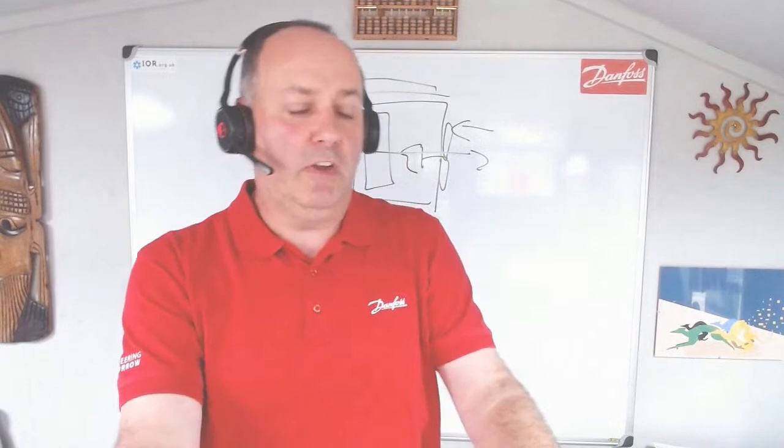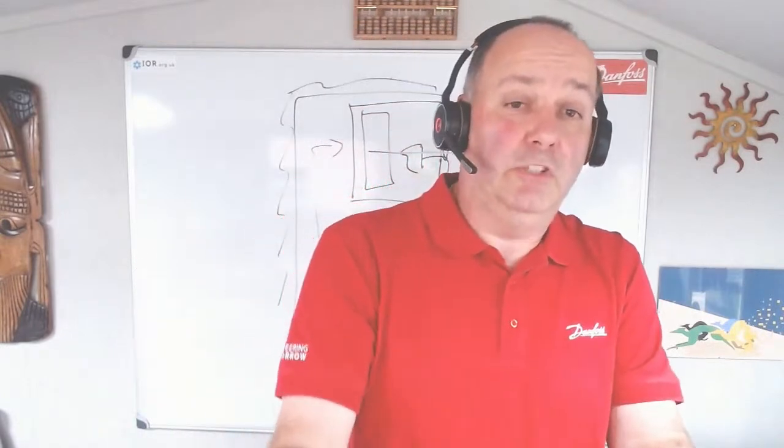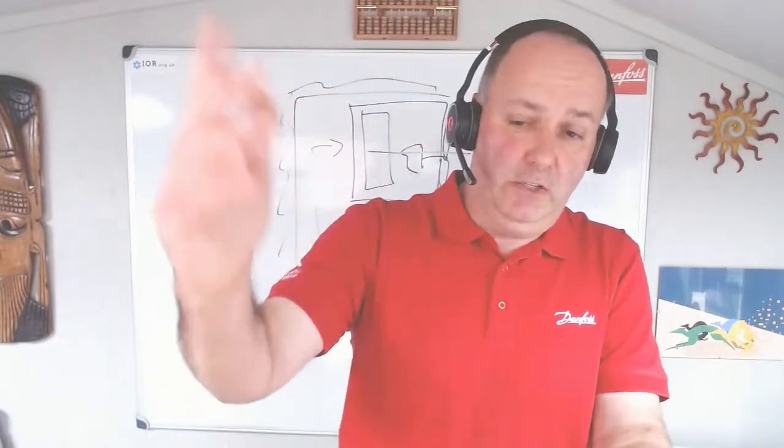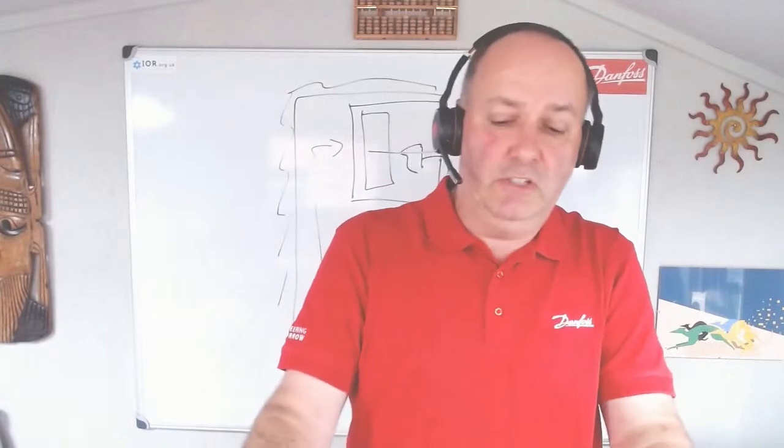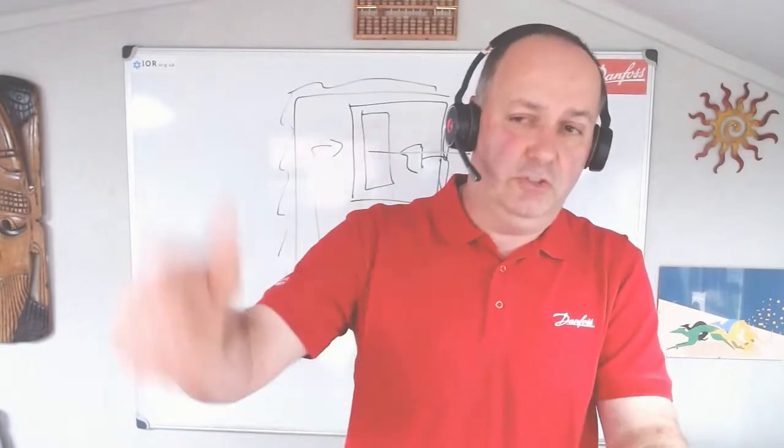If it's a three-phase fan, and I've been on site and this has happened, somebody's changed the incoming phases, they don't notice, they still see a fan motor going round, but it's actually going round the wrong way. So check the phase rotation on site, make sure the blade is actually tight on the shaft. Sometimes you'll look up at an evaporator and you'll see maybe, let's say it's got three fans, maybe two of the fans are going around fairly fast, and one fan is just sort of ticking along. And that's when the blade is actually loose on the shaft. So, things like that, most important.